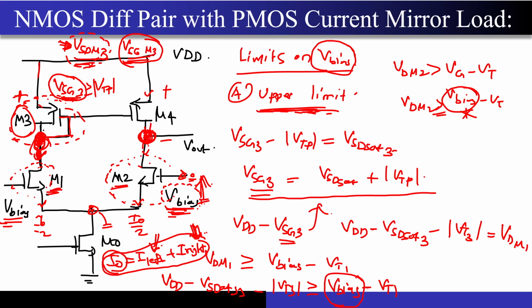First we started with assuming that the sum of these two is I0 under the right conditions. The reason I am telling you this is because I guess the confusion arose about why these two points have to be at equal potential, and why they should not change. That is where I guess the confusion got created. I was skipping that part, but that is what I have explained right now: why these two nodes should be at equal potential, or else we are contradicting ourselves. If the current on the left branch increases, then the right current should have decreased, but the increased current in the left branch is getting current mirrored, and that increased current again is getting dumped into the right branch.